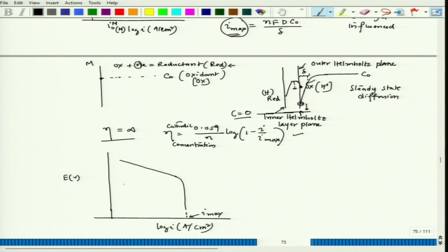So, if the metal dissolution line or the polarization line is interacting in the active part of the reduction polarization line, so this is reduction polarization and this is oxidation polarization, the interaction could happen like this. So, that time this would be my I corr and this would be my E corr, but if the interaction happens here,